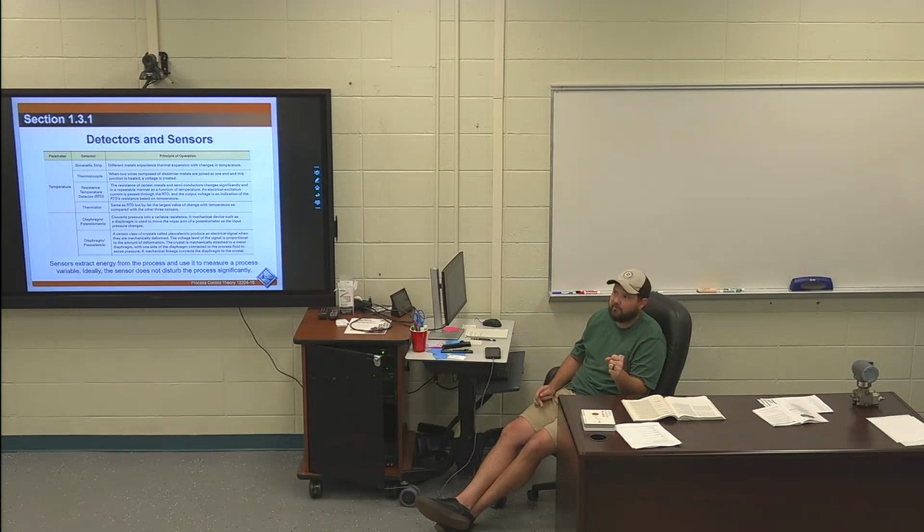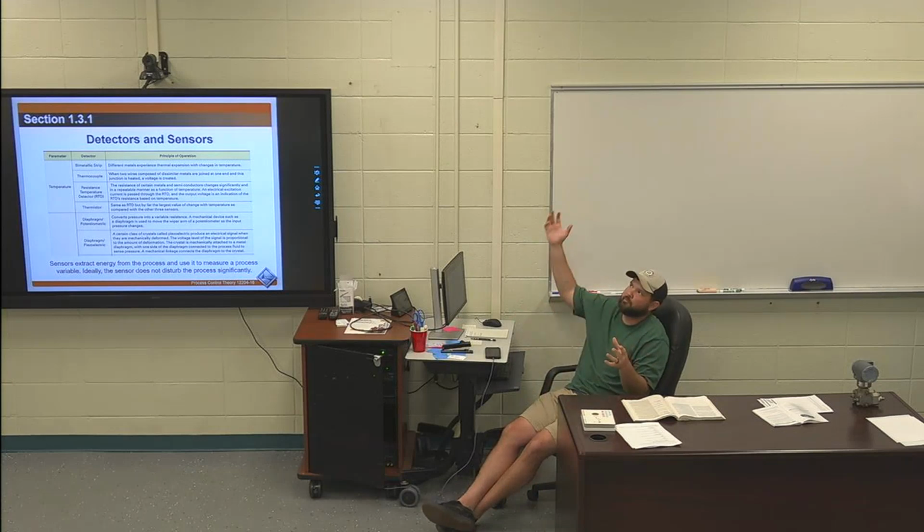So they're actually pretty good for turbulent tanks. A lot of times you can have a tank the size of this room that's being filled from the top, and water or whatever is just flowing into it, and the top is pretty turbulent. It's not good to have a float in there because that float's going to be jumping up and down, moving stuff around.